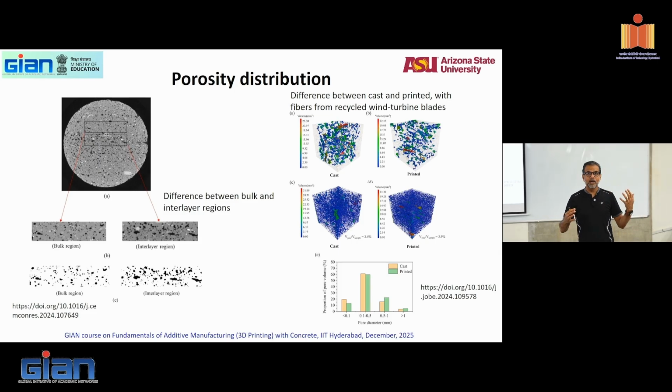If you're interested in doing research, some of these things are not high intensity work. If you have a reasonably good optical microscope and you know how to polish your surface reasonably well, you can do optical images, you can do ImageJ, and you can quantify layer and bulk effects very easily.